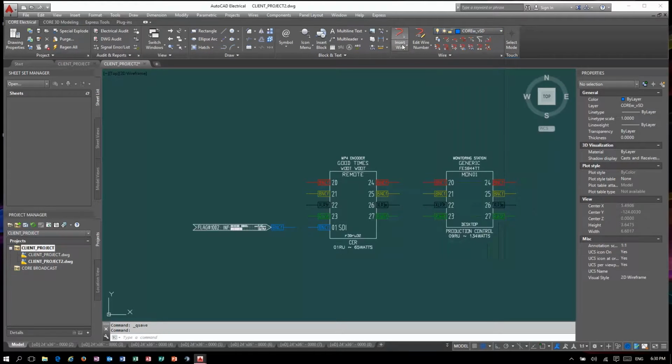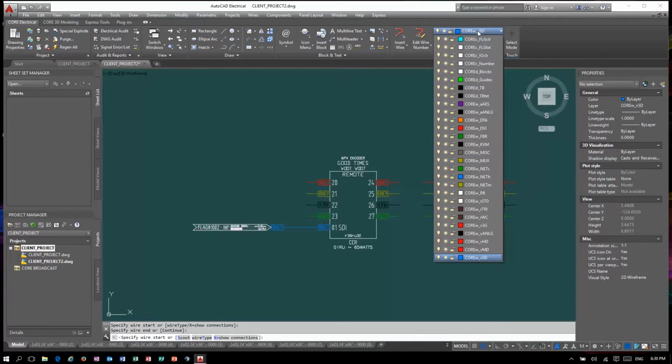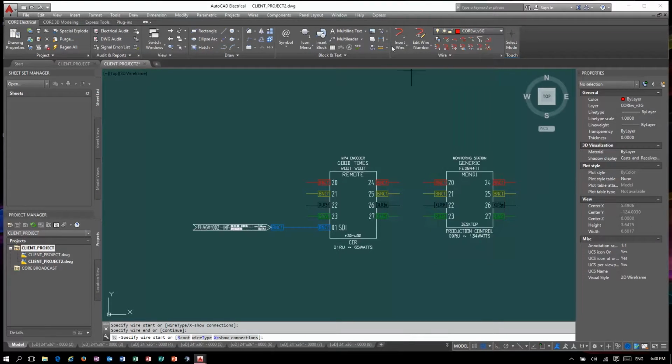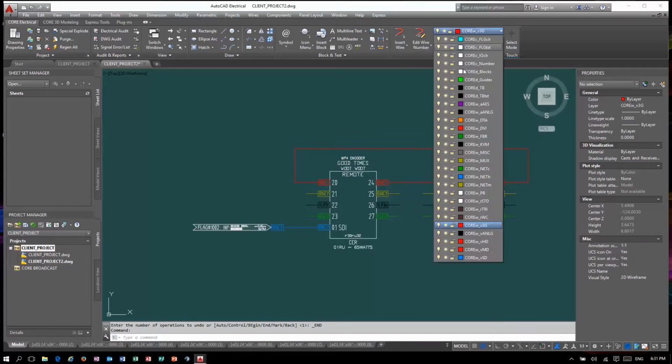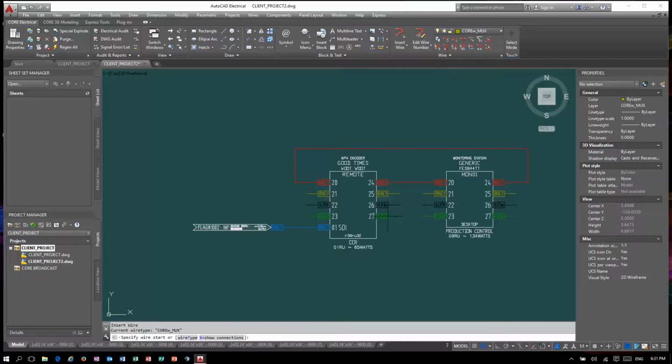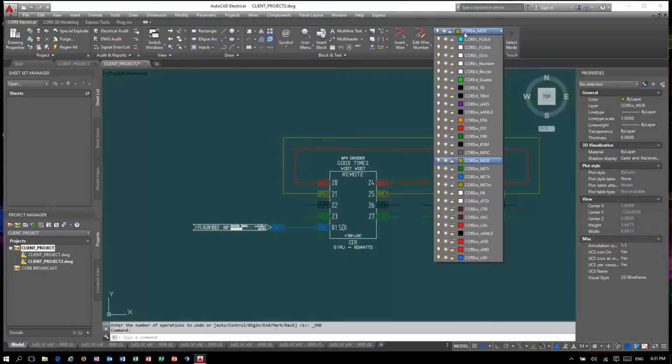Having been an Electrical AutoCAD user since version 2007, I can give you one tip to prevent major headaches in using the wiring tool. Select your wire layer, then immediately select the Insert Wire button. If you only select the wire layer before placing the wire in your drawing, it will default back to the previous wire selected, driving you crazy in the process. So step 1, choose your wire layer. Step 2, press your Insert Wire button again, then lay down your wire. Rinse and repeat.